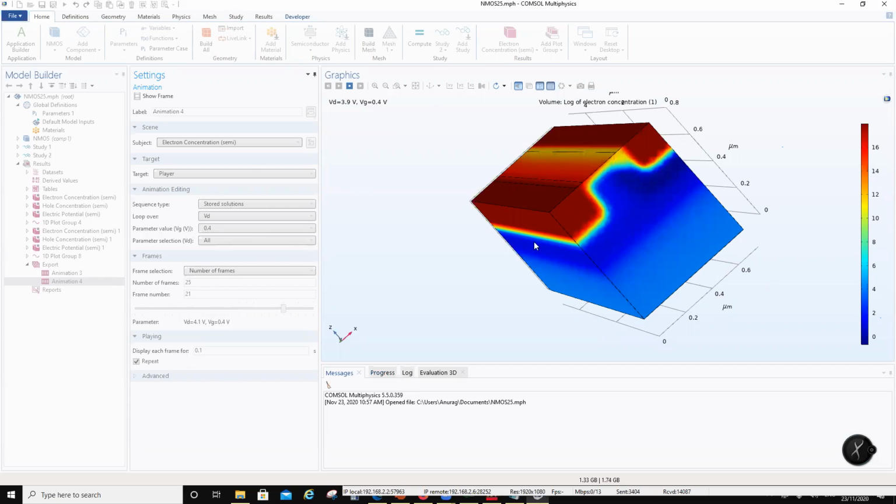You can at the same time do an inductor. You can basically do an elaborate circuit. You can do an entire chip in here. But then this simulation is going to take a very long time, and memory requirements are very large too, because there will be lots of devices. I have done a maximum of about 15 devices together in a circuit, along with the passives and actives. So this is possible in a multi-physics simulator like COMSOL, right?